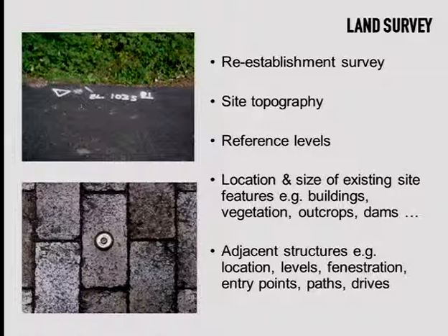Even flat pieces of land have got a slope on them. It's very hard to pick with your eye. So in order to determine what the heights of the ground are, because we need to establish where our driveways are going to be, where our floor heights are going to be, we need to know what is the ground level. Okay? So we need to know site heights. So we need reference levels.